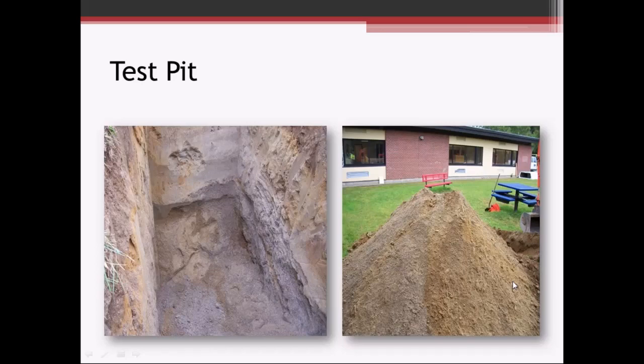As I mentioned, test pits are typically dug with an excavator, which gives a good representation of the soil at shallow depths, as well as groundwater conditions. We're usually limited to about 8 to 12 feet in depth, depending on the size of the excavator. One of the drawbacks is that it does disturb a rather large area versus a soil boring. So if test pits are dug within a building footprint area, it's important to make sure the test pits are properly backfilled.